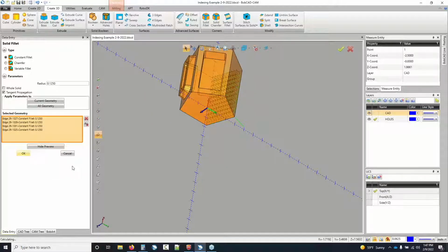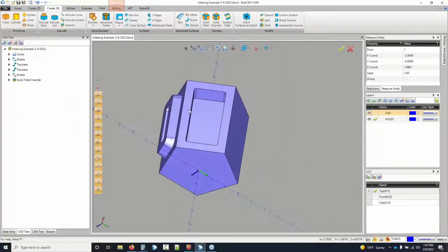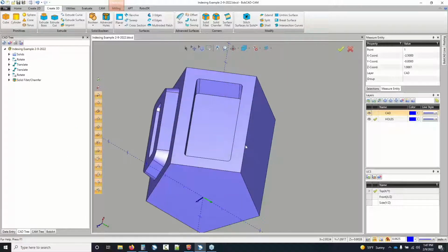Now, if you didn't do this, you don't have to do this. There's really no benefit to this. If I go in with a 1/2 inch tool to rough it and a 1/4 inch tool to finish it, that 1/4 inch tool can't cut a sharp corner. It's not going to try and shove it even further into the corner. It's just going to basically leave this exact pocket. But now I have a proper representation on my solid model of what I would expect to get when I run this my normal way.